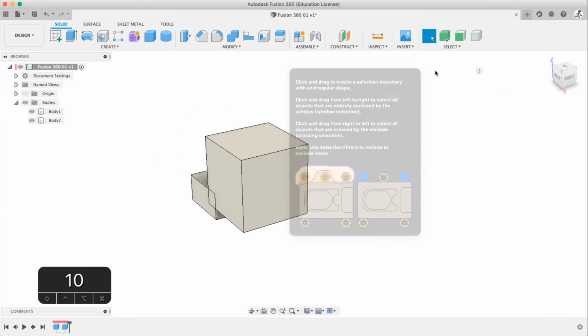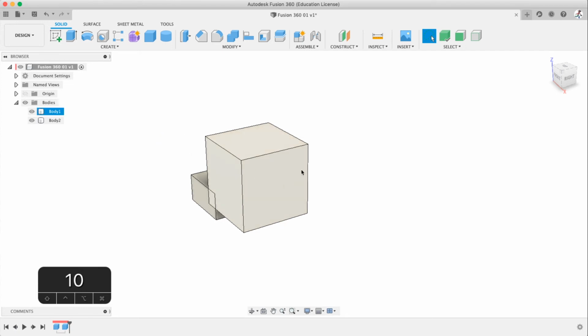Going back, there's freeform. This one is if you have complicated objects. Let's say you have a bunch of nuts and bolts on the edge here. You only want a certain number of them. You can wrap around them. But anything inside this yellowish window gets selected. The whole thing gets selected. If I do this and everything but this tiny corner on the left here of this object, it will not be selected. That's that. And the last one is the paint selection, which is just a drag over and it becomes selected. If you hold down Shift, it adds the selection. If you don't hold down Shift, then it won't add the selection, just kind of does a new one each time. And that's the basics of our toolbar.